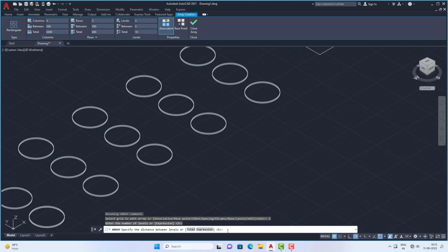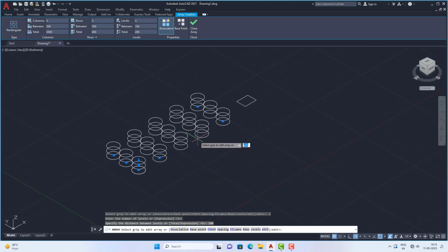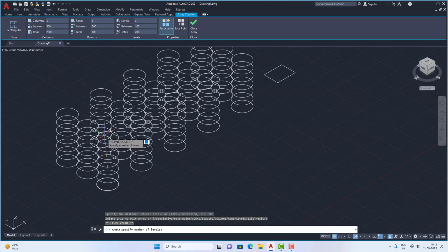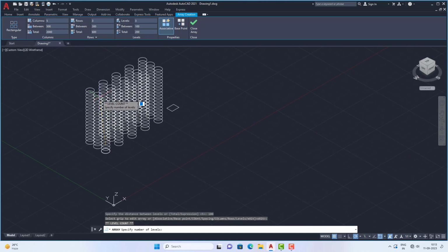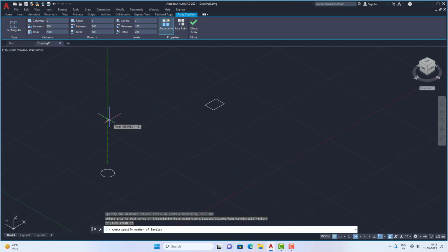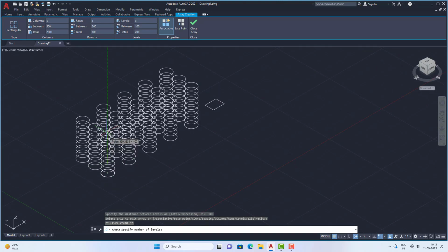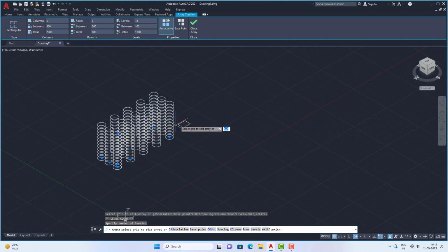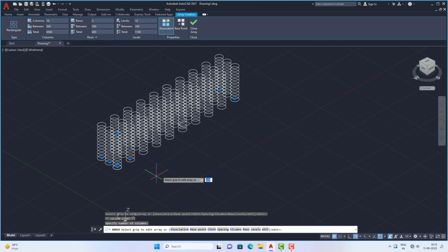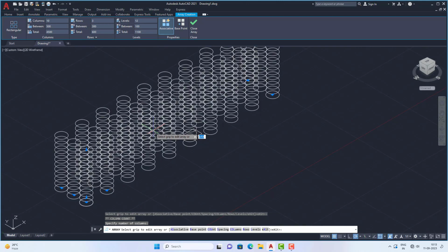See how the levels are creating. So layer by layer it will be creating, and click here and just drag your mouse so that those will be added. The levels will not be visible in 2D, so you need to change the view to 3D. And if you click anywhere, that will be added. And if you click here and drag your mouse to increase horizontally and click anywhere, like that the levels will be added in the Z direction.